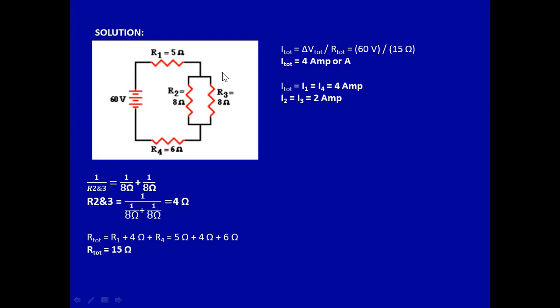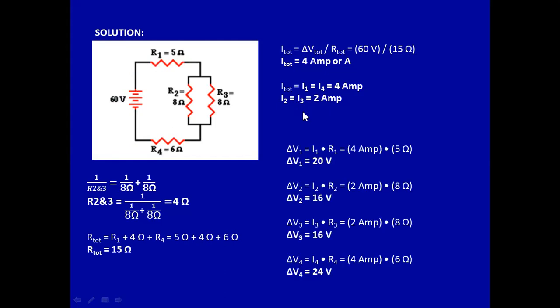Okay. So since we have simplified the value of your resistors here as 4 ohms, the whole connection now is connected in a series configuration. Okay. So since this is series configuration, your total current now would be equal to the current passing here, here, and here. Okay. So your total current is equal to this one as 4 amperes, which is the same with the resistors on 2 and 3. If we're going to further simplify this one, this gives us the following.